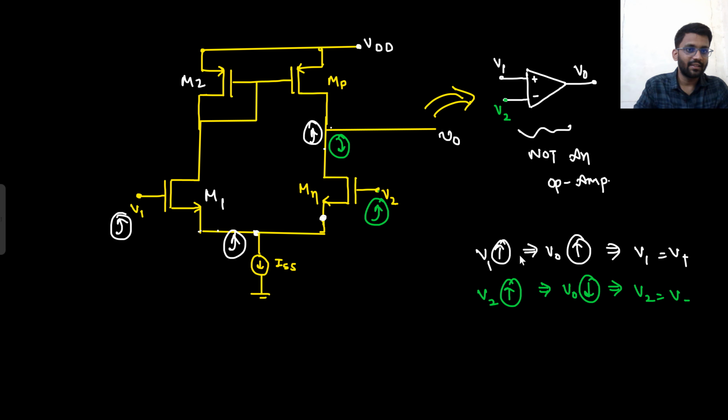And in the GATE examination this year in 2024, this question came where they shorted the output to this node. They made this circuit and gave the gain A value. They asked what the output voltage would be. V1 minus V0, since this node is shorted, into A is equal to V0. When you solve this, you get V0 equals A upon 1 plus A. The A value given was 40, so 40 by 41 would be your answer.